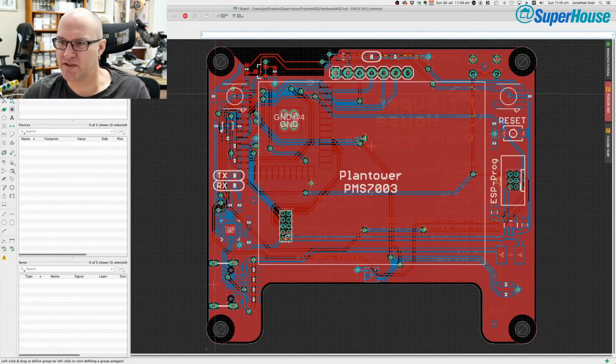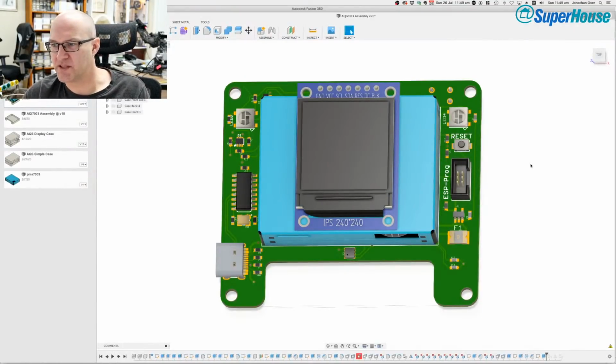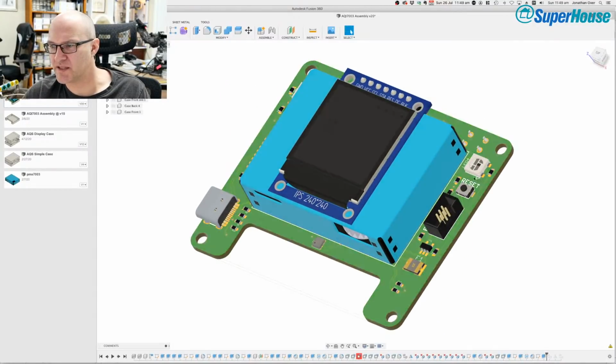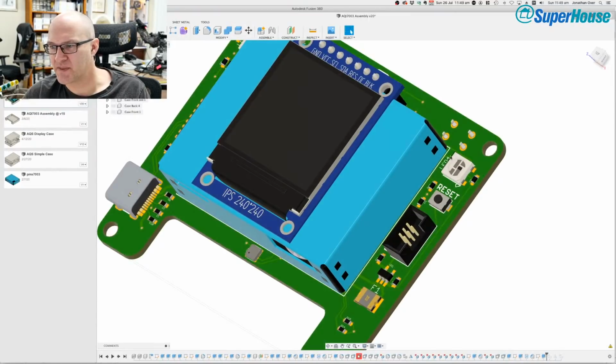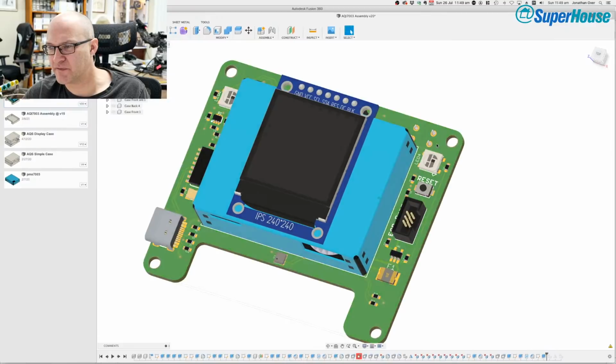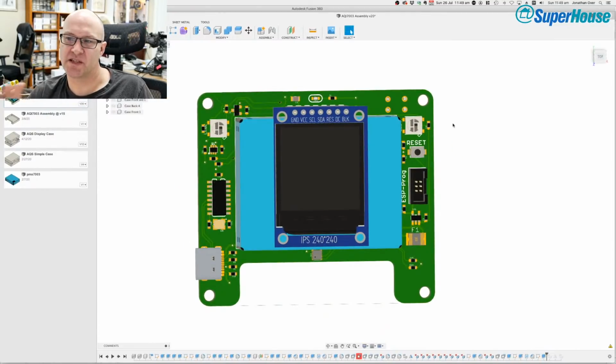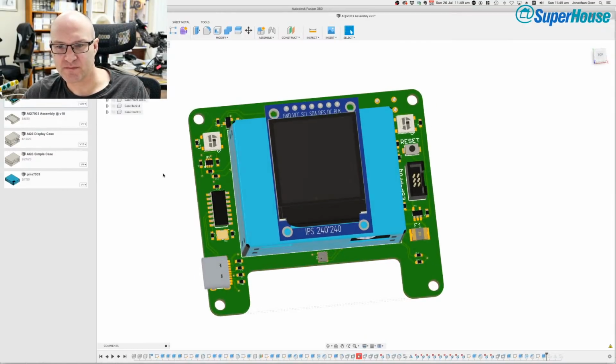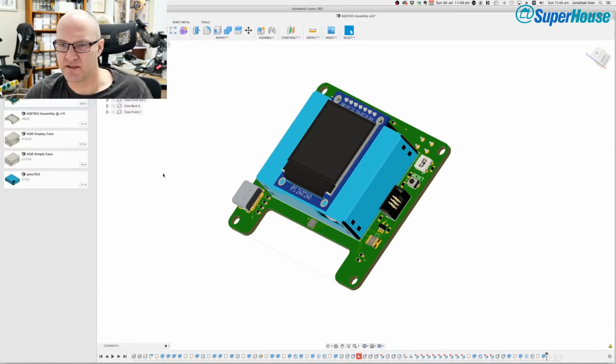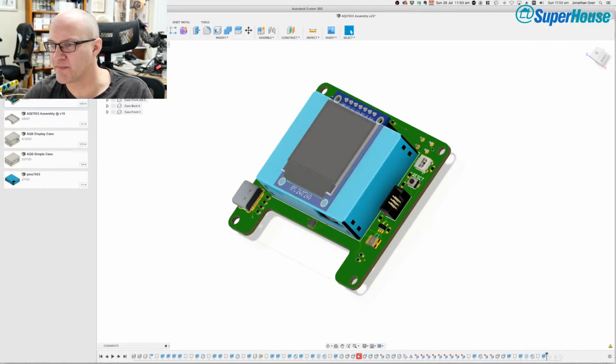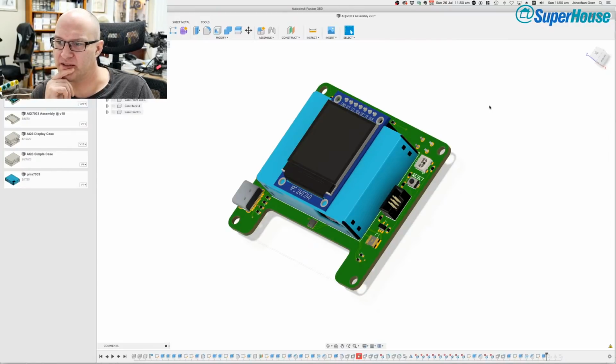And you can see up here that the LEDs are mounted up there, but it's really only when you switch into the full 3D view that you start to get an idea of how the different parts of this fit together, and the LEDs here being a fair way back from the front, which could be okay if it means that you've got a semi-transparent case and you want diffused lighting. But yeah, I just find that it helps me to understand it a whole lot better having those 3 schematic, PCB and 3D views all open in front of me all at the same time. And even from quite early on, as the project is developing, I suppose the traditional process of electronics design is extremely linear.